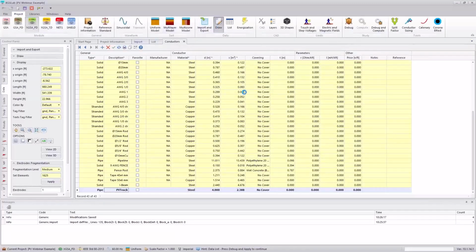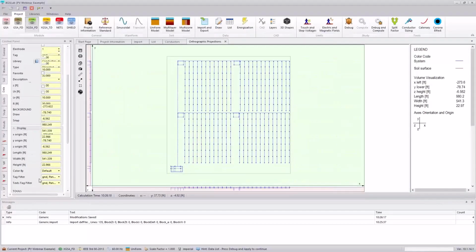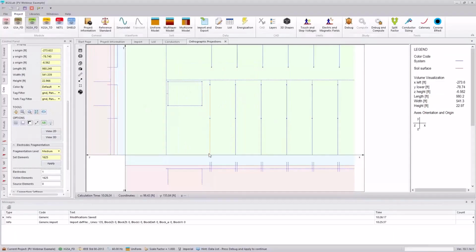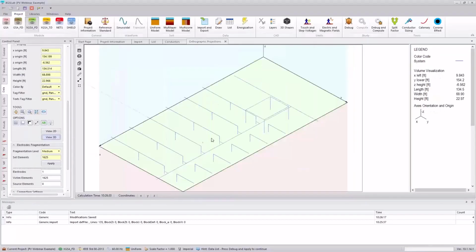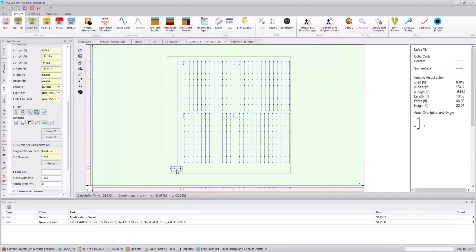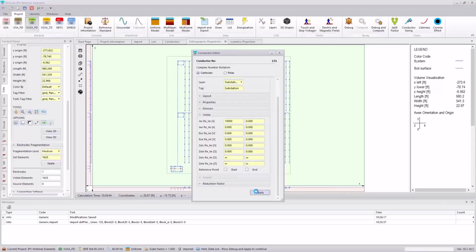And when I import this from a CAD file, I have my system layout represented here. So we can see, if I zoom in, this would be something like the ground loop around my inverter. Here we have represented the connections from a dedicated ground to my first post, and then this is my tracker, and then each of the posts that go into the earth that support that tracker in the air. So I'll just inject a fault so that we can look at the voltage that occurs across the system.